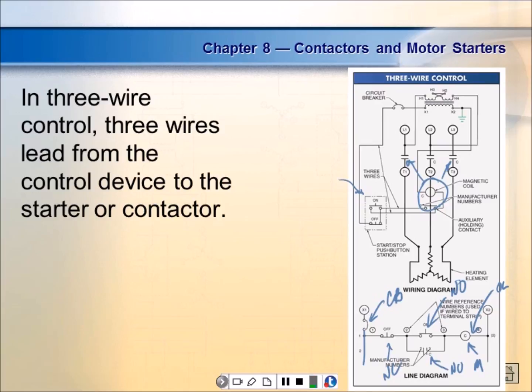And of course, this is not a motor. This is just a three-phase heating element out there. A three-phase heating element is nothing but resistors. And resistors, the current they run on is the current they start on, right? You understand what I'm saying? Where motors, they start with more current than they run with. Are we okay? Yes or no?